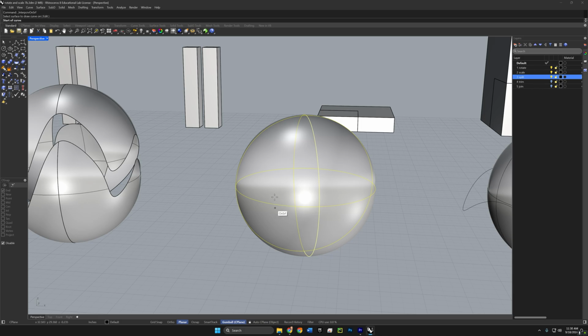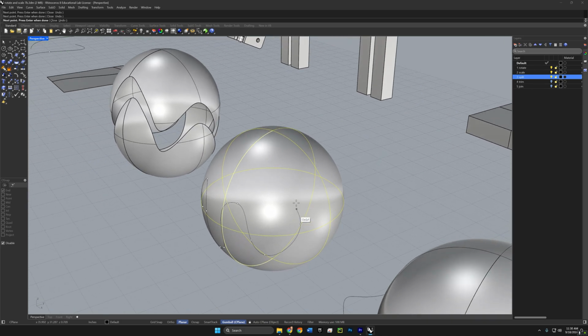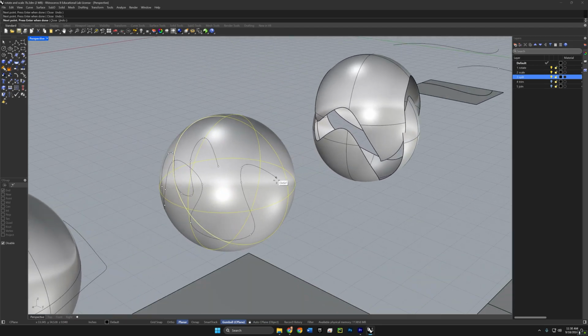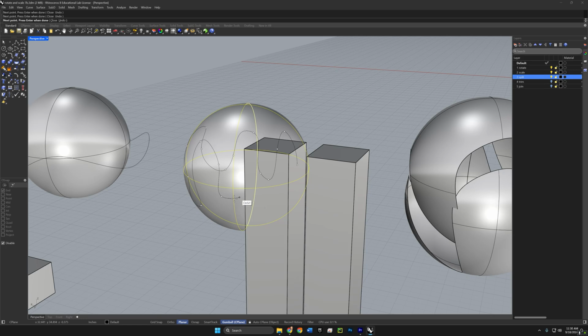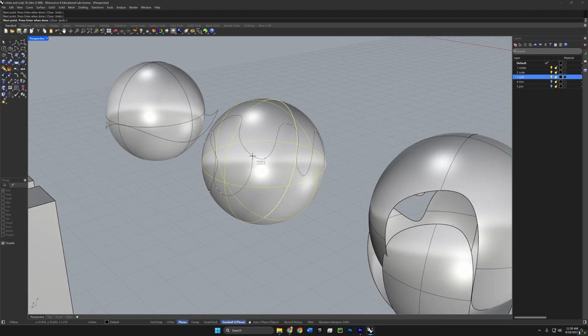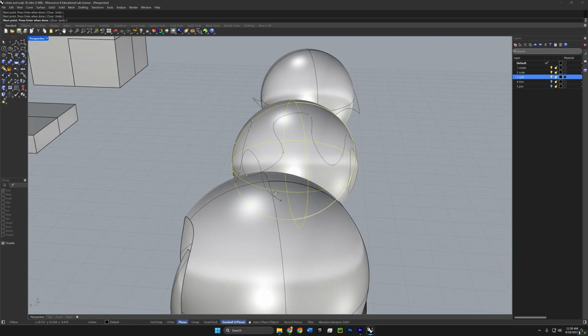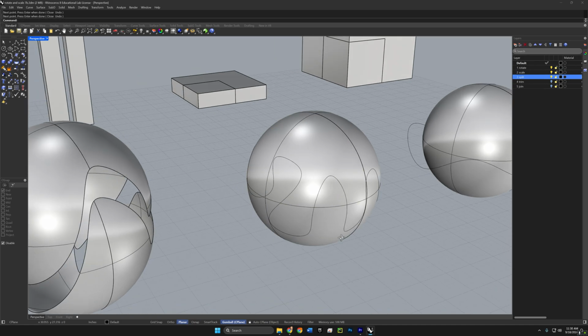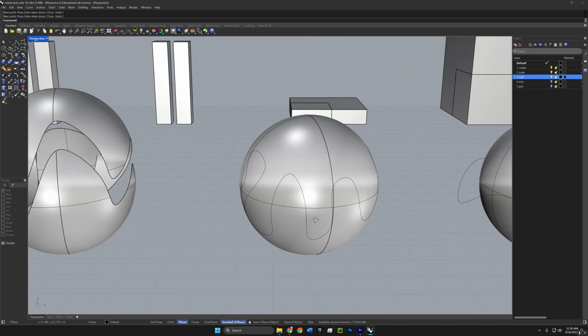this sphere. And then we can start to create whatever kind of curve we want that snaps in various places on the sphere. And we just need to make sure that we come all the way back around to end where we started. To snap back to the point we started from, we'll hold Alt to do our end snap, or a point snap here, and push the right mouse button to finish the command.